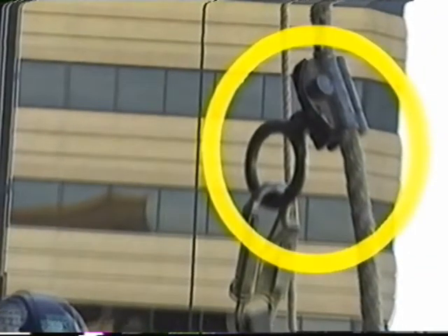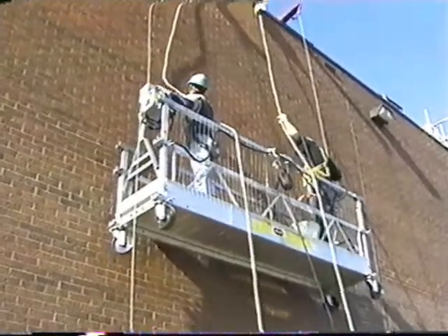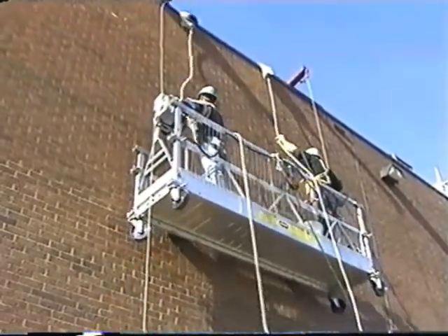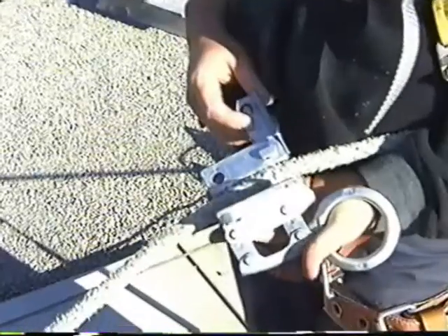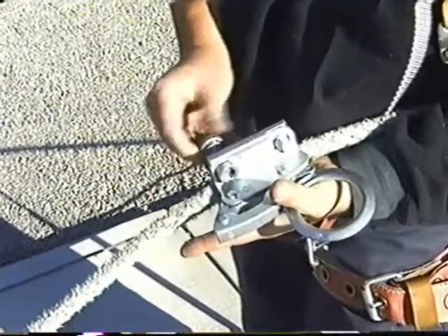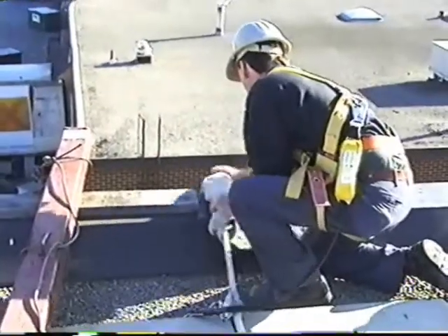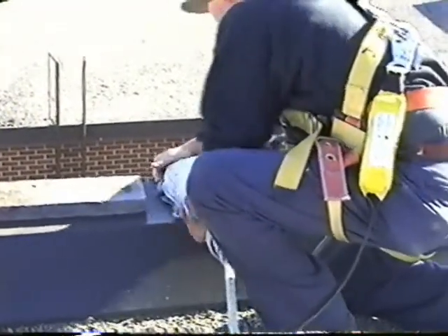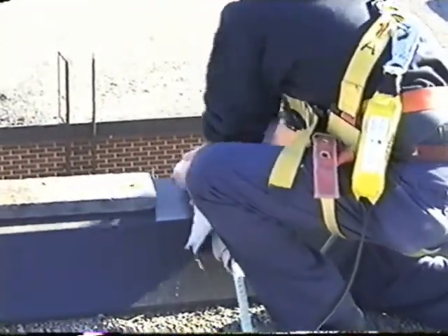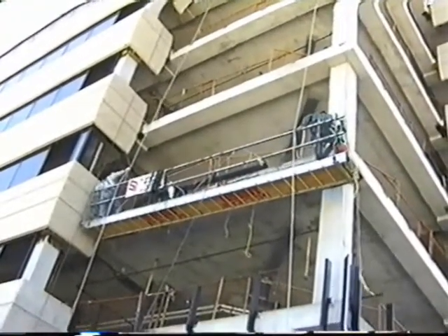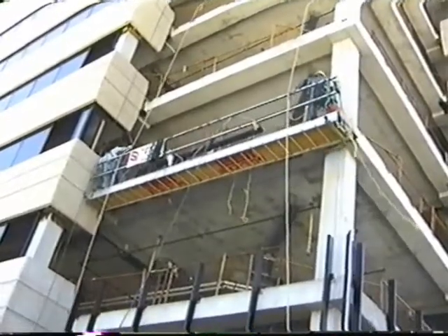The rope grab is designed to lock onto the lifeline when a fall occurs. The most common type of lifeline is the 3-strand polypropylene blend, 5/8 inch or 16 millimeters in diameter. Always make sure the rope grab is installed correctly and is matched to the size and type of rope being used as a lifeline. Arrange your lanyard or lifeline so that it won't be cut, chafed, abraded, or exposed to hazards such as extreme temperatures, flame, and abrasive or corrosive materials. Remember, only one person at a time may use a vertical lifeline.